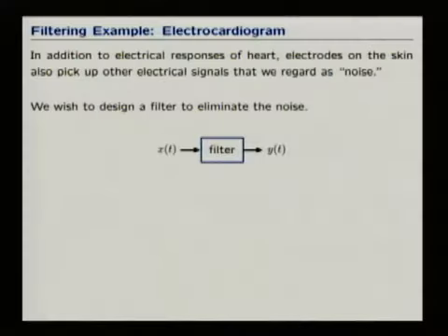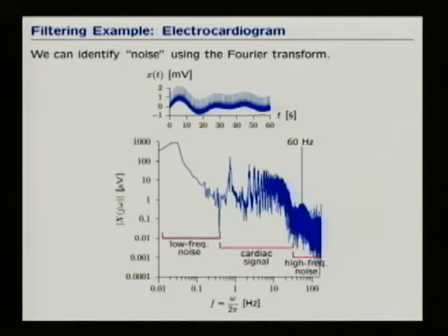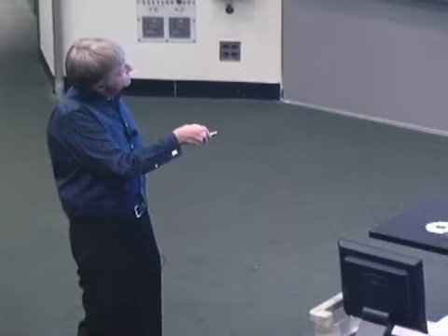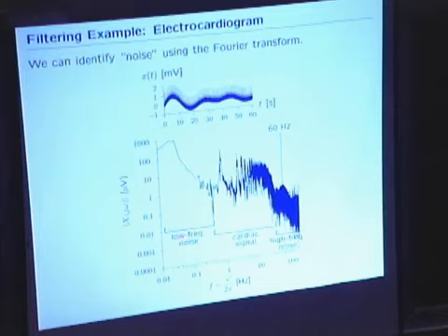So you see those. So the idea of filtering out the part of the signal that results from the EKG is completely non-trivial. And it's very useful to think about it in the Fourier domain. And absolutely everybody does it that way. If you were to take the Fourier transform of this waveform, you would get a waveform that looks like this, which looks perhaps more complicated, except that you can make some sense out of it. Hearts beat about 60 or 70 times a minute, depending on how athletic and how old you are, which means that it's the components around 1 hertz or bigger that are coming from the heart.